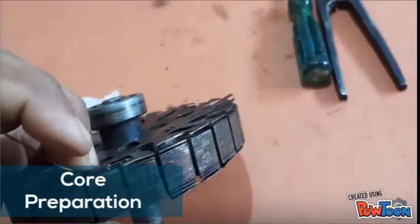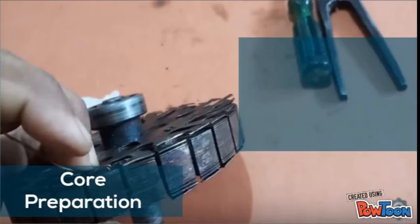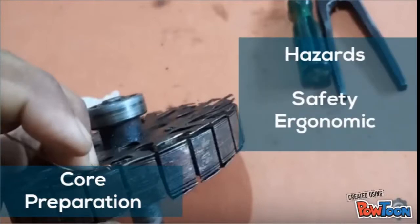And then we have here the core preparation, where the selection of the correct type of core depends on production quantity, production rate, required precision, required surface finish, and the type of metal being used. The hazards that can be found here include the stator core and the empty boxes, which are classified as safety and ergonomic.